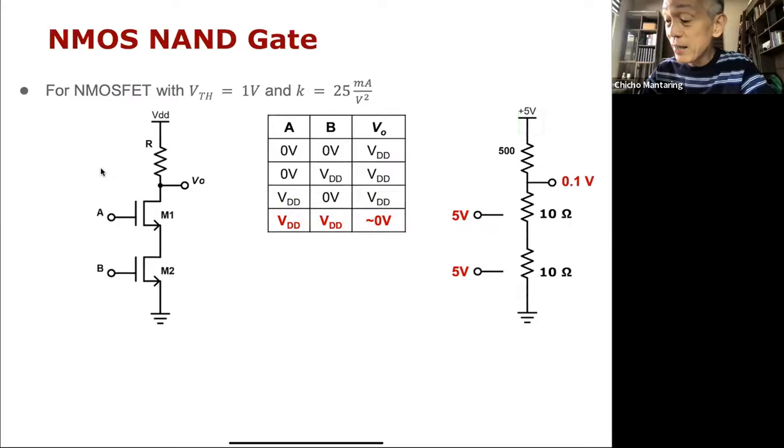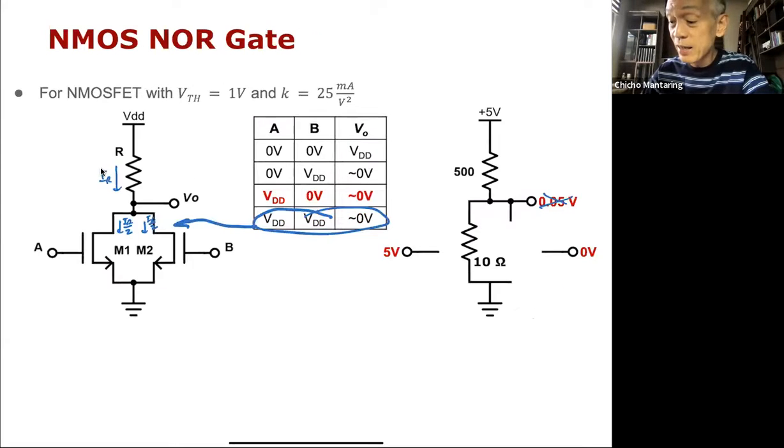And then again, the NAND, okay. This is wrong. The NAND, this is now in series. And then the complication of the NAND is the voltage here now, as you put more and more in series, will increase. And you have to make sure that as this voltage increases, it does not exceed this, no?